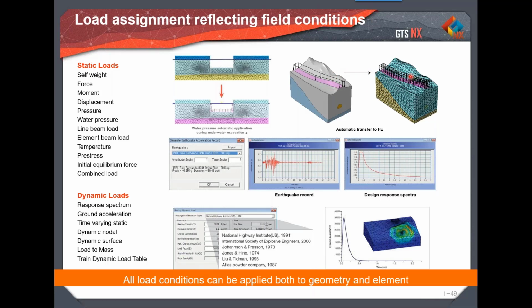and you can get the results accordingly. And in the case of loads, you can go for concentrated force, concentrated moment, and even concentrated displacements as well. And you have an option to go for initial equilibrium force. So what is this? I will tell you right now. The thing is, in situ stresses in the soil play an important role, and in situ stresses can be determined by using various techniques like the K-naught technique or gravity techniques and so on.